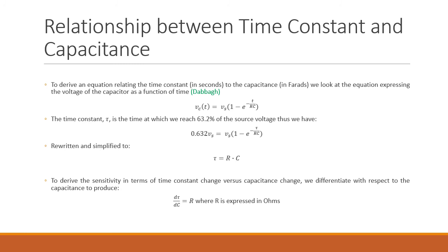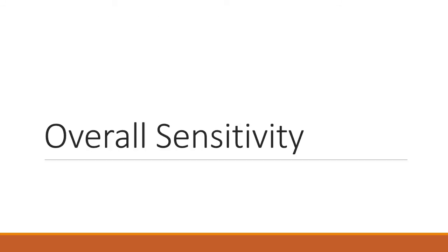To derive the sensitivity in terms of time constant change versus capacitance change, we differentiate with respect to the capacitance to produce the following, the final equation, where R is expressed in ohms. Finally, we take a look at the overall sensitivity of the arrangement, which is the change in time constant, which has a unit of seconds, as the height of the water, measured in meters, changes.